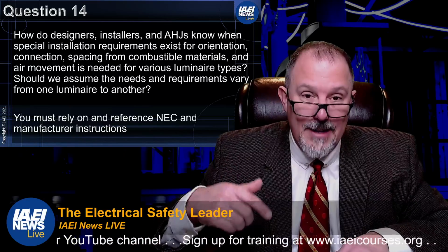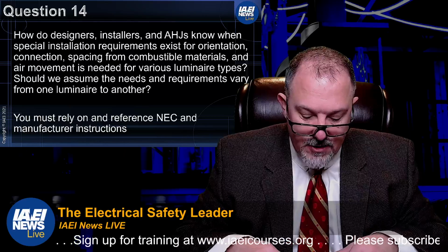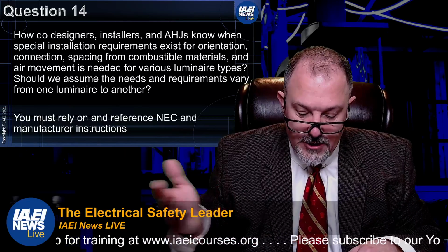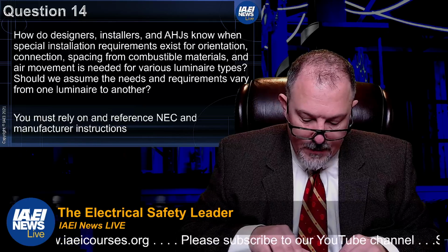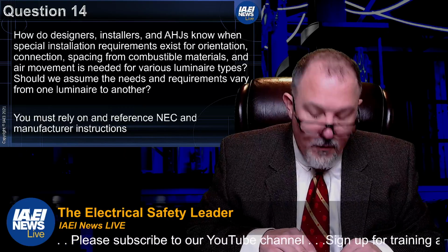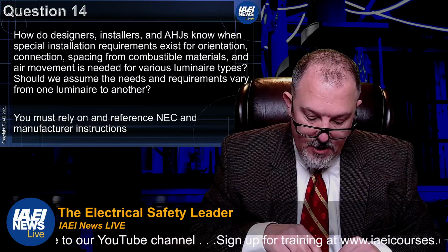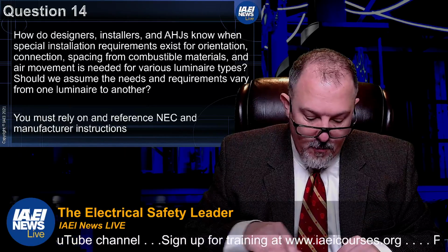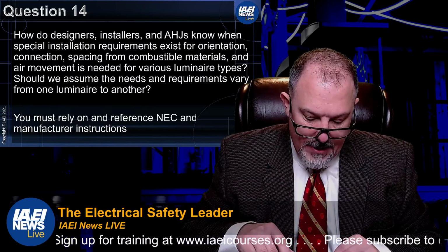That's part 12. Special provisions for electric discharge lighting systems, 1,000 volts and less. This is your electric discharge lighting. Thermal protection, fluorescent luminaires. This is in 410.130(E). The ballast of a fluorescent luminaire installed indoors shall have integral thermal protection. Replacement ballasts shall also have thermal protection integral with the ballast.